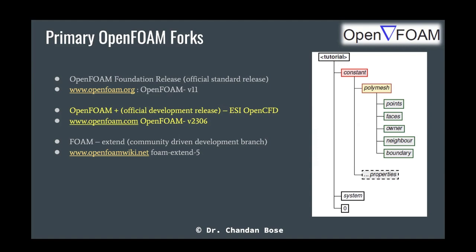Now, people who have already used OpenFOAM, can anyone tell me what this 0 folder means and why it is named 0? Initialization. Yes, correct. So in this 0 folder, we keep the boundary conditions and the initial conditions at t equal to 0. Okay, and that's why this folder is called 0.